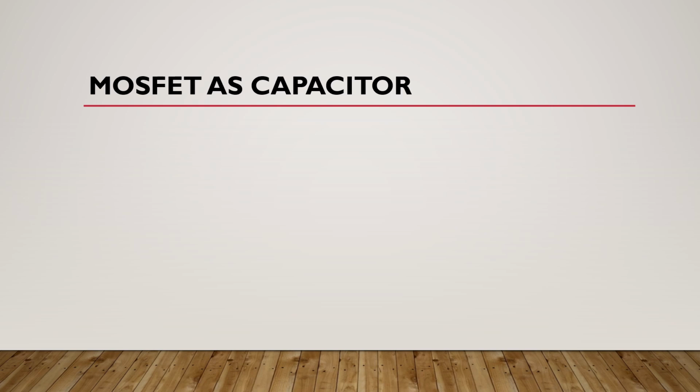Now we will understand how MOSFETs are used as capacitors. There are four types of capacitances of MOSFETs which exist in both N-type and P-type MOSFETs. First type is CGS, which is gate source capacitance.